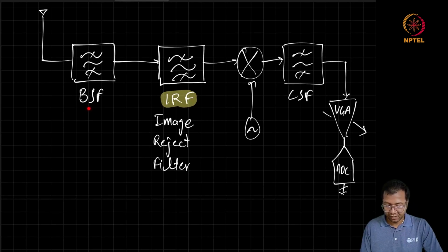So we can already see that multiple filter stages are present in the circuitry. Each of these blocks, if it is not adding any power to the signal, adds loss, which we have already seen. And this band select filter, if it is designed using these passive components, will be adding its own loss.